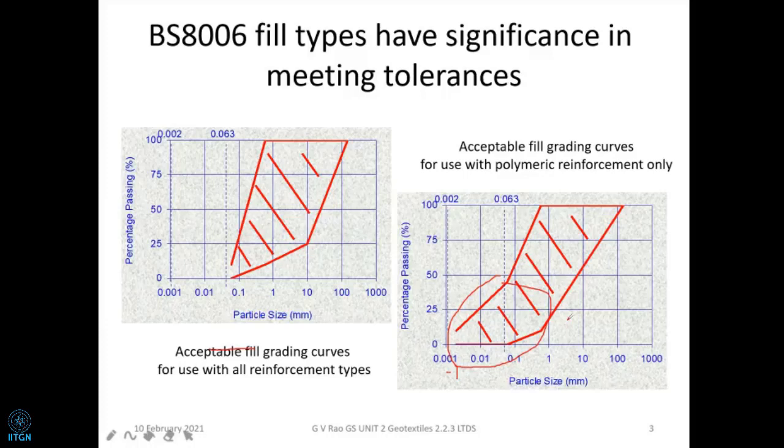But if the foundation soil is really clayey and soft, or loose sand, or medium dense sand, then a bearing capacity issue may come up. Particularly if it is clay soil, we probably have to either go deeper or change the soil by ground improvement methods. We are not dealing with that now. For most cases, with reasonably good foundation soil, this structure doesn't need any foundation at all, because it rests directly on the foundation soil. There is no other intermediate structure.